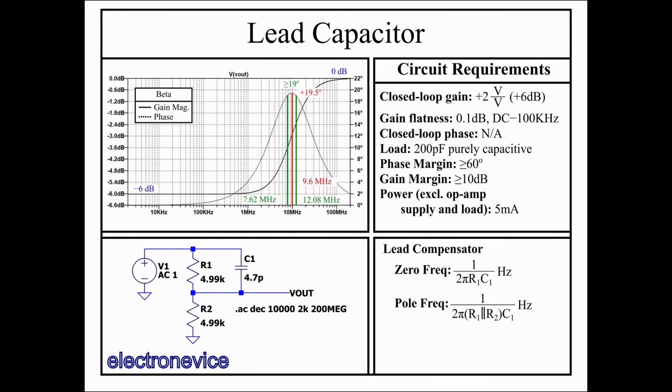You may note that we have neglected to include the 0.5 picofarad parasitic capacitor across R2. We can do this because we successfully pushed that pole out to a much higher frequency, and thus we can ignore it and still get a pretty good approximation of the transfer function of the feedback network. This is especially true since we're not solving for the optimal value of the lead capacitor, just getting close and verifying through the loop gain simulation.